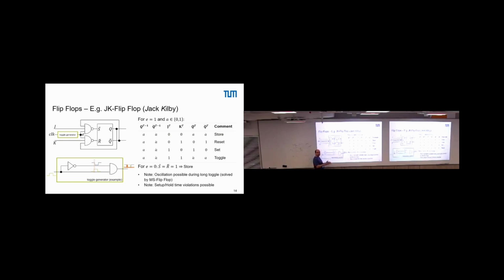Okay, so if you have this short enough, it should be okay, right? So from a theoretical perspective, we could build here something that generates a glitch. Could look like this. And if you build such a glitch generator that is designed so that the time is very short for switching, then this here is disabled before the signal feeds back, and you only toggle.